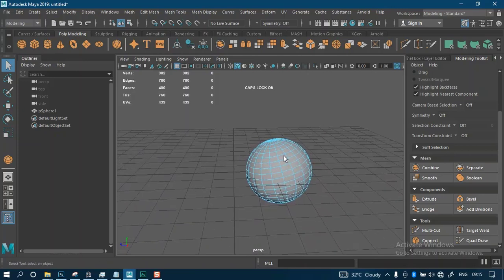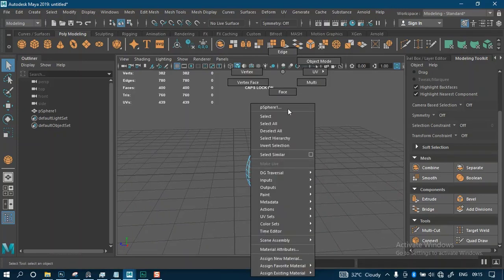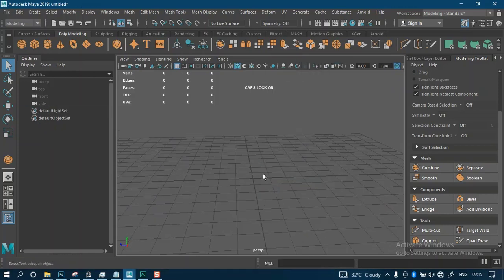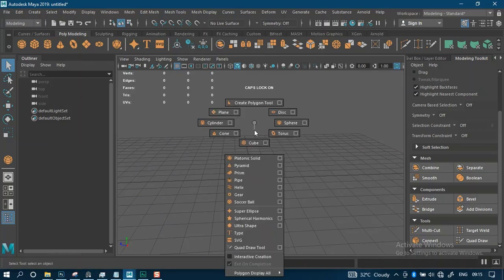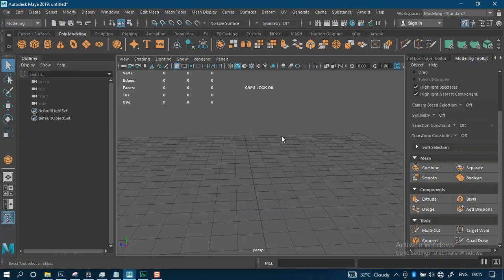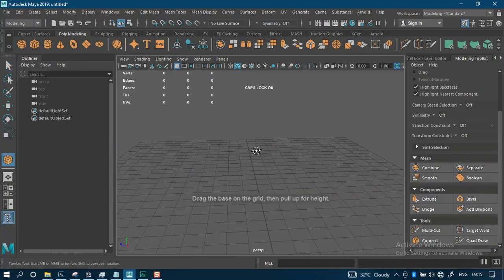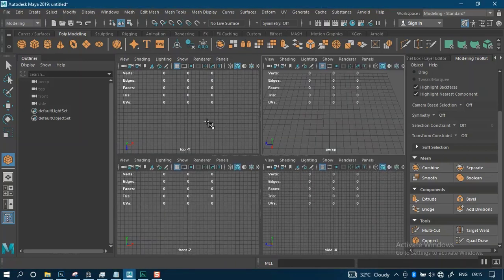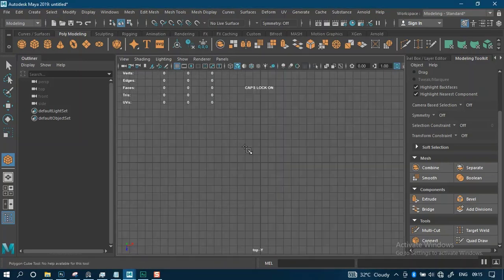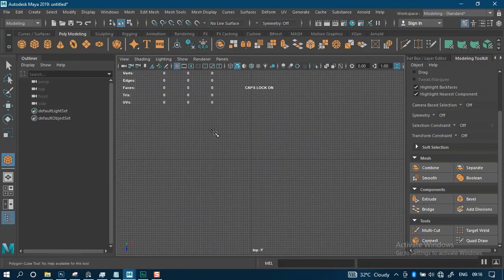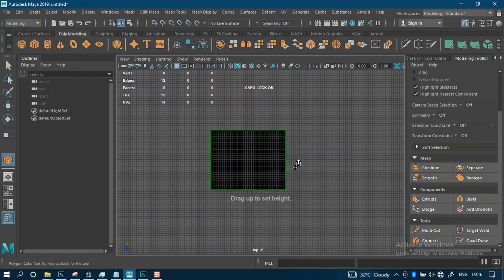Okay. So I'm just going to delete this for now. Then let's drop in a cube. So I'll hold Shift, right click and hold. Make sure interactive creation is turned on. Shift click, right click and hold. Let's create a cube. So I'll hit the space bar, go to the top view, then I'll just zoom out like so, and I'll just create a cube like this.